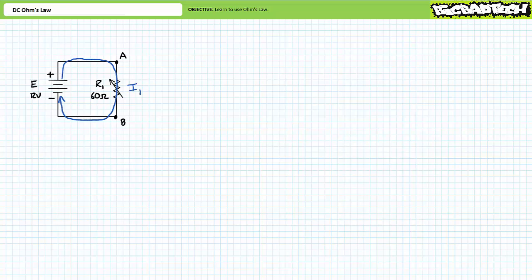Second, the voltage source E and resistor R1 contact each other at nodes, where a node is a point of common connection for two or more elements. Customarily, I indicate nodes using letters. Let's call the top node A and the bottom node B. Nodes, again, are common points of connection. Let's now differentiate between active and passive elements in electrical circuits and discuss how to differentiate between and annotate voltage rises and voltage drops.